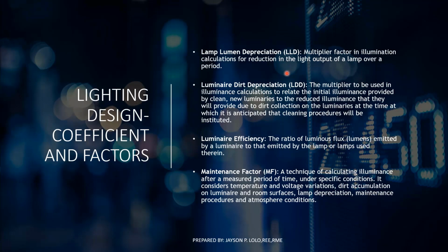This LLD was formerly called the maintenance factor, as indicated here in the definitions at the lower part. It is also called the light loss factor. So we have three common terms: light loss factor, lamp lumen depreciation, and maintenance factor. They are all the same.